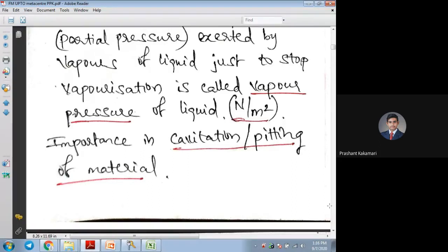So at a given condition, when steam is flowing or high pressurized water is flowing in the pump with not-filled flow or incomplete flow, or when tap water is filling a bucket, this bubble formation will start because of the low pressure at given points, and these bubbles will suddenly burst at the surfaces of the pipe, or the enclosed impeller channel of the pump, or between the enclosed channel and the turbine flow.